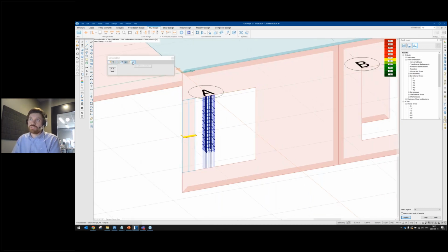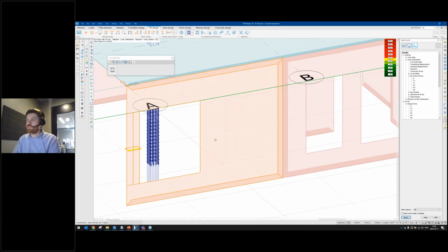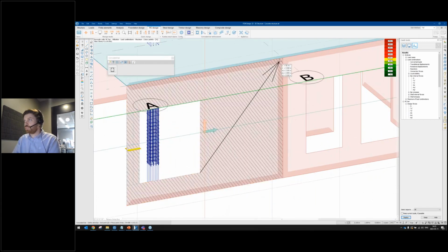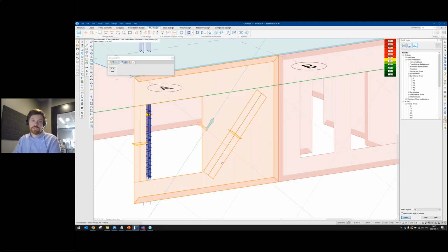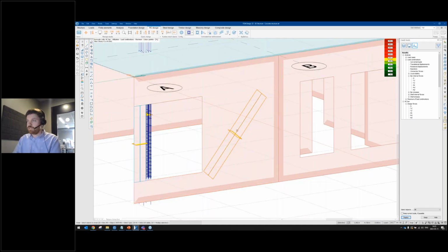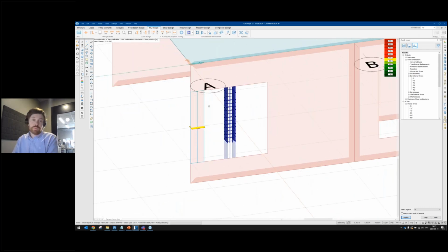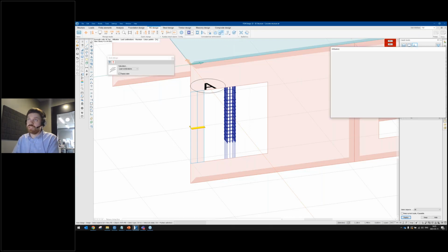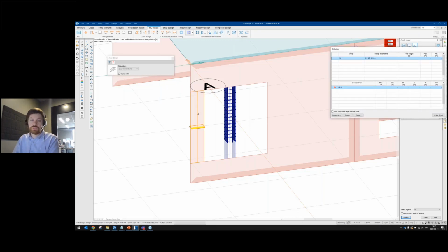But you can also use it in a skew direction, a user-defined direction. If you have a more complex geometry, you can actually place a concealed bar diagonally in the skew direction, so it doesn't have to be like X and Y or something like that. But let's remove this and continue with this. Otherwise, besides the definition, it works exactly the same as the bar design. So I can use the same parametric reinforcement, manual reinforcement, and auto design to apply reinforcement in the concealed bar.